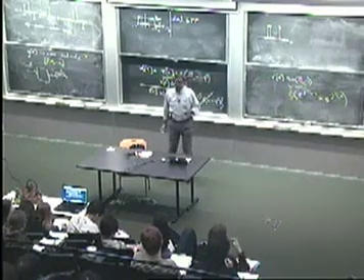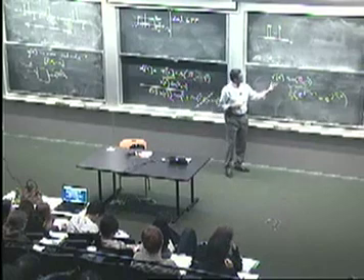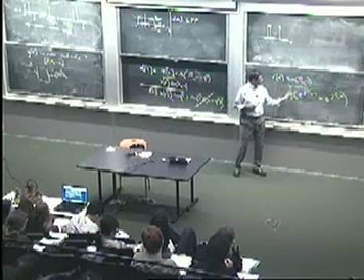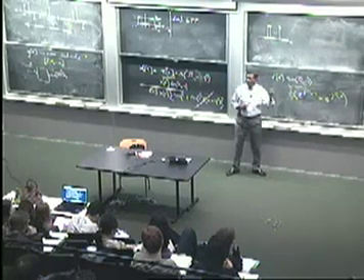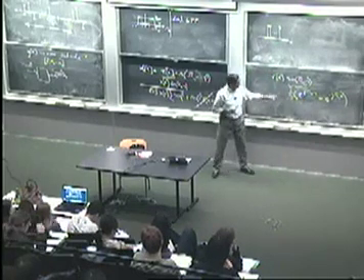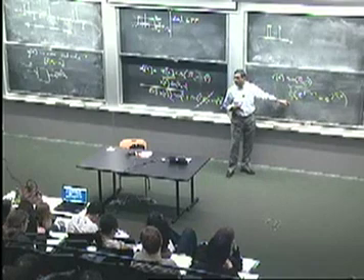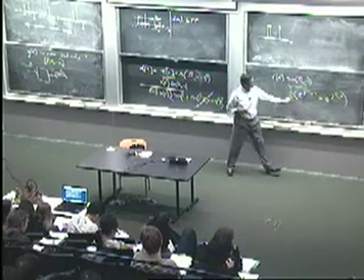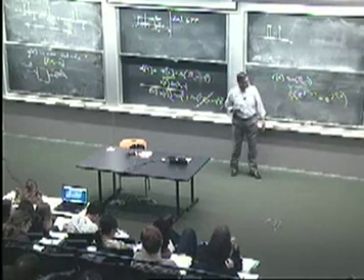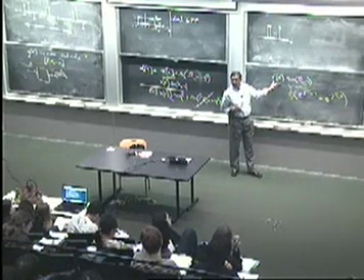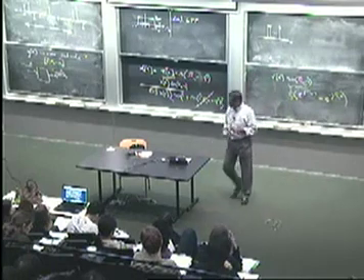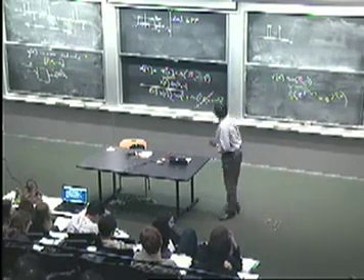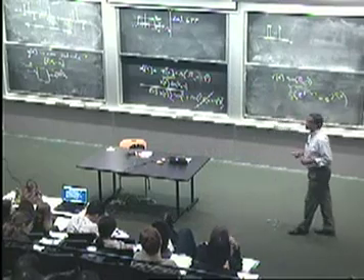So in the spectral domain, what happens? Well, you've got R of n multiplied by 1 over 2j times this first exponential. In the spectral domain, that does a shifting and a multiplying by 1 over 2j. And then you've got this term doing the same kind of thing. So you're going to have a shift of the spectrum of R of n in the frequency domain and a scaling by 1 over 2j.